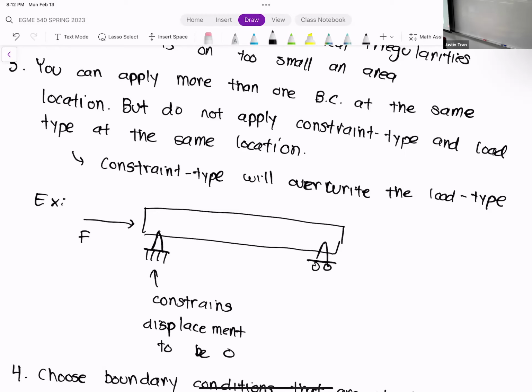Yeah, that's a good question. When you have random elements, you can run a stochastic simulation. What that means is that instead of a set value for the force, you sample it from a distribution. The wind magnitude has a certain average and deviates by this much. The direction has a certain average and deviates by this much.